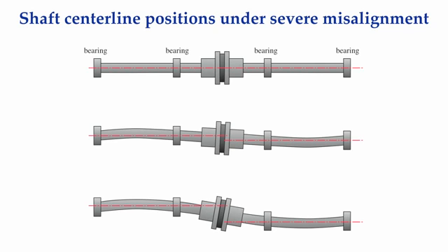Be very careful not to misinterpret the illustration. The shafts in the middle and lower position are not permanently bent. They are just elastically bending. There is only a one-letter difference between the words bend and bent, but there is a huge difference in what those two words mean. Also be aware that elastically bending shafts do not produce an out-of-balance condition.